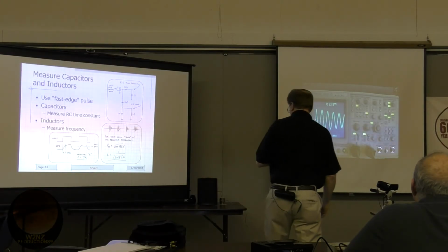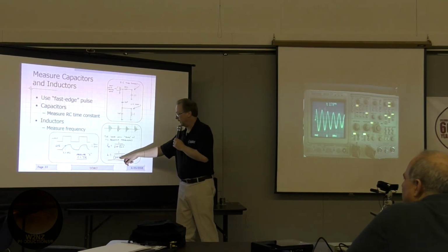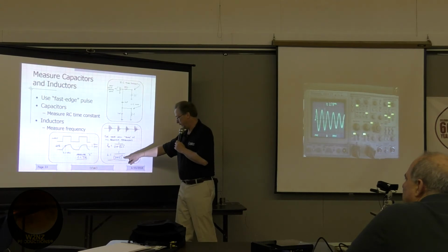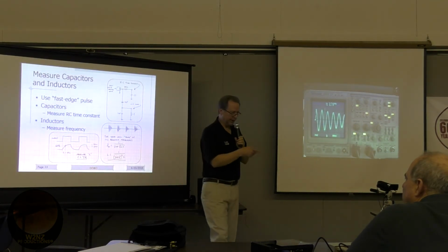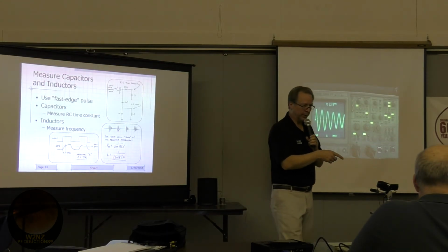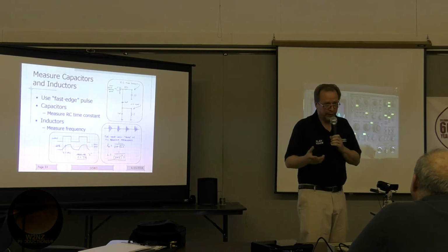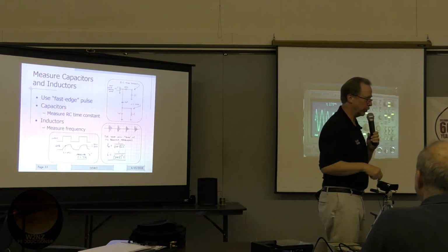And the math, again, is a little bit of a complex formula, but take 2 pi times that frequency, 2.78 megahertz, square that quantity, multiply by my known capacitance, and invert it. If you run that math, it winds up being about a 3.3 microhenry inductor. Okay, but that's a simple way. Well, a little bit more math, but you plug it into Excel. You don't have to worry about programming it again.